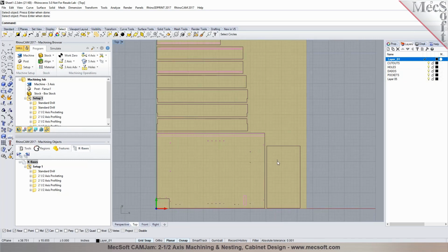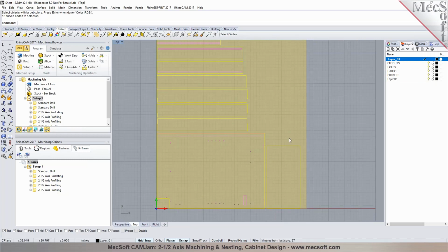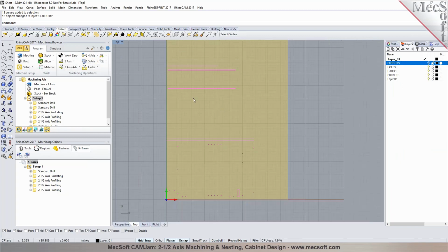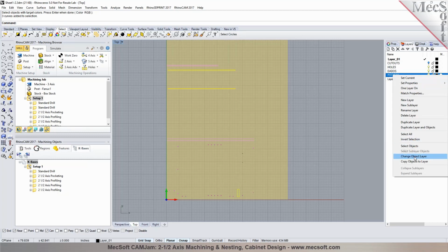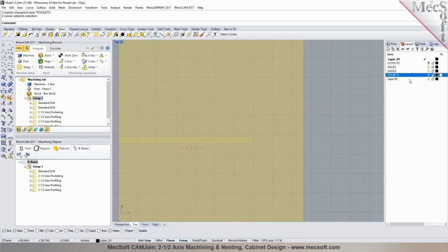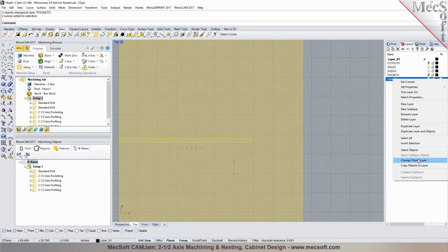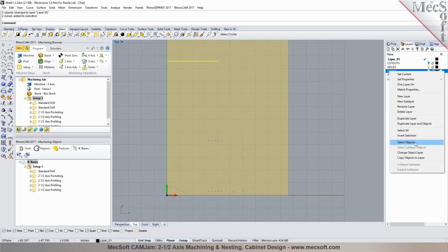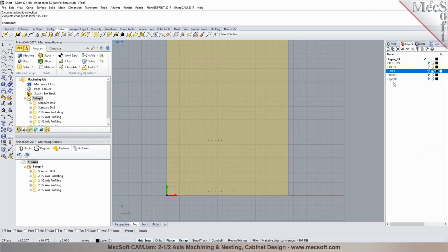And now in Rhino, I'm going to select objects based on color and place this on layer called cutouts. I'm going to use these pockets in here and move all these 3 pockets into a layer called pockets. I'm going to select the dado right in here. I'll put it on layer 5. And the smaller dado, I'm going to put it on layer dados. Okay. And I'm going to call these dados large.